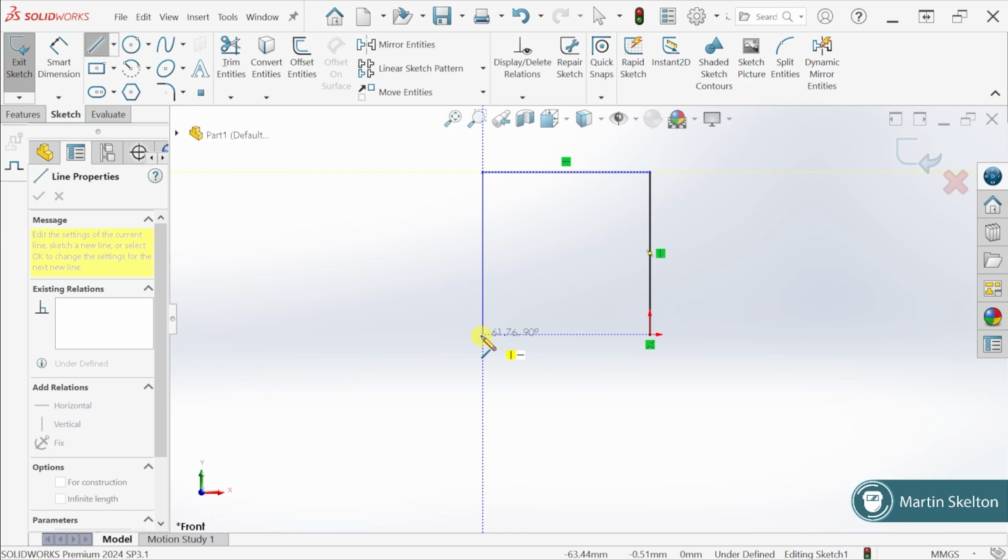The problem with underdefinition is, if you modify something else on the file, you could possibly move something that you weren't expecting to move on the file. It might be only moving 1/4 millimeter, you will never notice. And then when that piece goes to actual manufacture, that's where the issue starts. Things might become out of line, etc. What we would do is we'd fully define and lock in all our sketches.